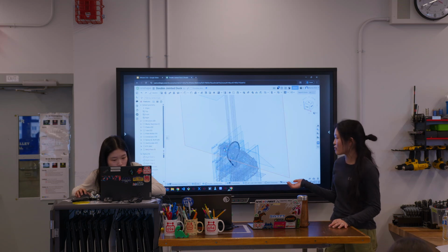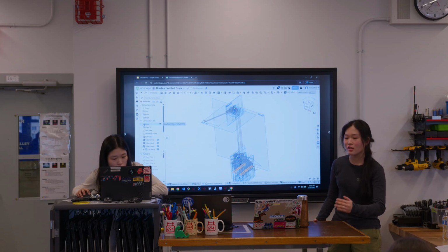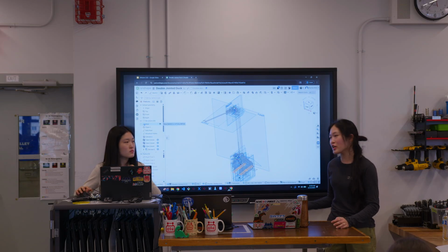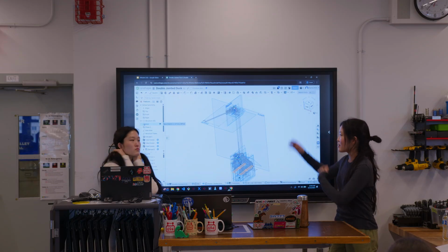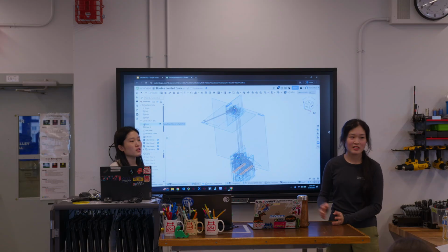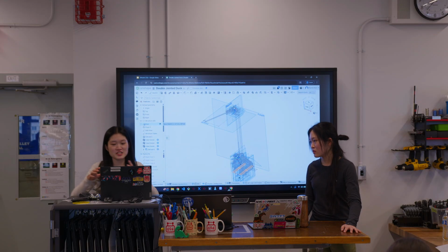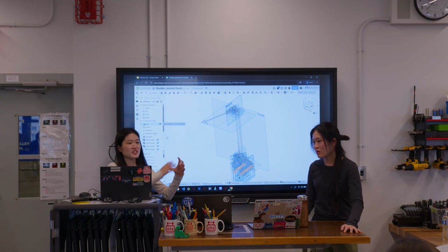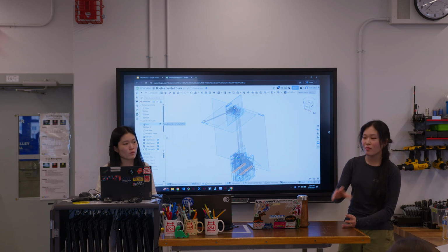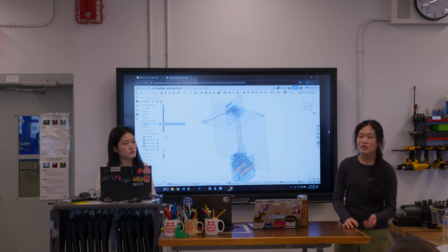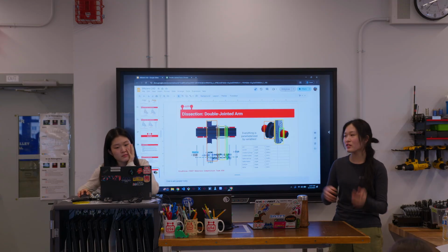So it also depends on if you're doing FTC. What I realized when I was doing FTC was that everything in the robot master sketch has to be a lot more specific. So I actually had the axle sketches in the robot master sketch, so there's no clear distinction, but it's kind of a general idea. Even if you make your mechanism master sketch, you might retrace and be like, I actually need this sketch before I made this, because this sketch is linked to this sketch. And some other mechanism lead might be like, I really need this type of feature from your mechanism, so can you add that to the robot master sketch? So it's not like you do this first and then you do this. You might go back and forth, and there's no really clear line between it.